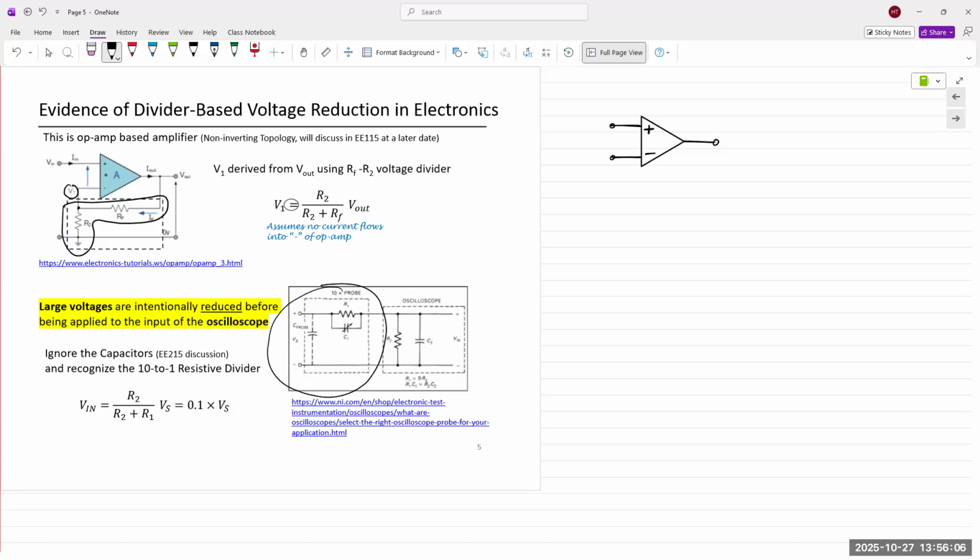in there. If you use an oscilloscope probe that has a 10x or 100x setting on it, then the mechanical switch or the manual switch on the end of the probe, those settings must match the settings that you set on the oscilloscope itself. If there's a mismatch, your answers on the oscilloscope will be multiplied by 10. So instead of measuring 5 volts, you'll be measuring 50 volts. If something like that does occur in the lab, 100% is that there's a mismatch in the settings in the oscilloscope and the manual switch. Okay, that's something to keep in mind.